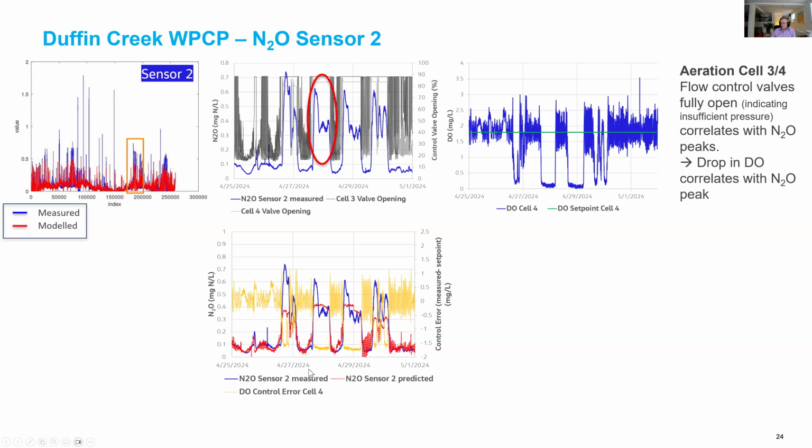The interesting thing for me is during the peaks, you see that the measured N2O spikes but then drops again, right? So DO is still 0 or near 0. It looks like some kind of adaptation, and maybe that's a new state that the organism is in. Is there maybe some adaptation happening? Because you see that every single time: DO drops, N2O spikes, DO stays low, but somehow it comes down and seems to get to a new state. Maybe if that took longer, it would go back completely.